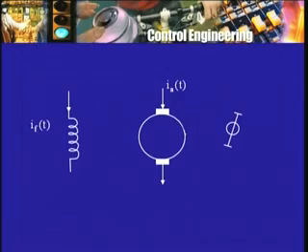So Phi will denote the magnetic flux in the air gap, and the way in which we think about it is that the field current gives rise, that is the flow of the current in the winding produces magnetic flux Phi in the air gap, passing of course through the core of the armature. The armature is also made of magnetic material, and thus there is a possibility of an interaction between the armature current which flows in the conductor and the flux in the air gap, as it is called.